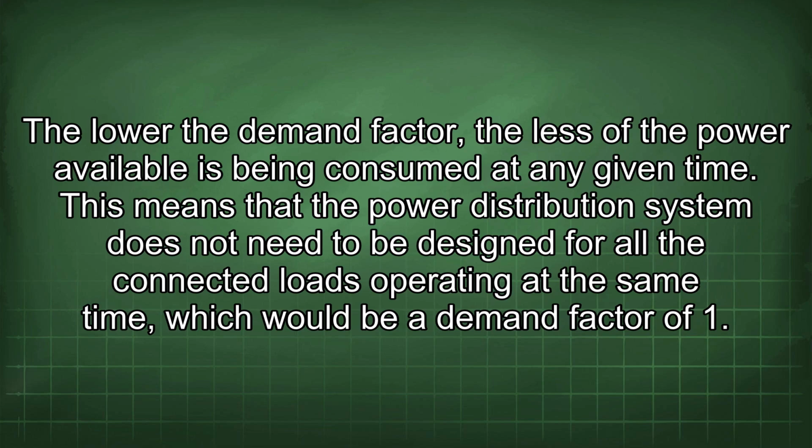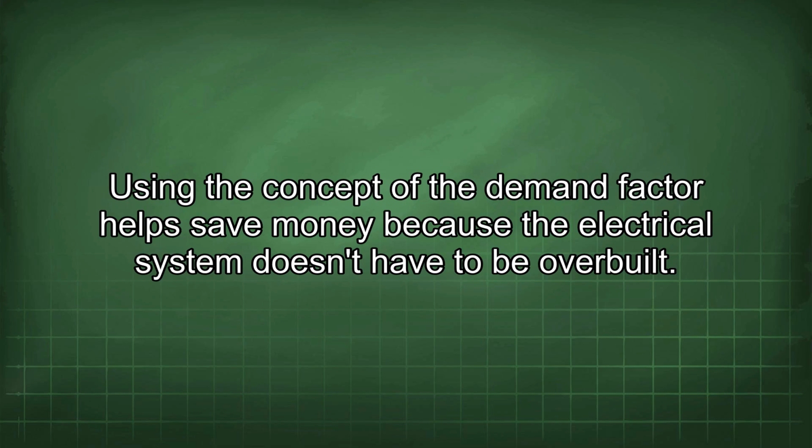This means that the power distribution system does not need to be designed for all the connected loads operating at the same time, which would be a demand factor of 1. Using the concept of the demand factor helps save money because the electrical system doesn't have to be overbuilt.